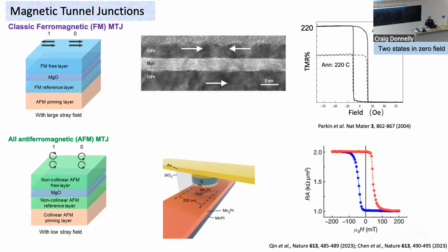However, there's one drawback. Today, actually, it turns out you have to switch the direction of magnetization by passing bigger currents, and these bigger currents deliver angular momentum and can apply torques on these layers. And that current today is 2 times bigger than the current available from a minimum sized transistor. So this is very important. We need to be able to reduce that current to fully take advantage of these devices.